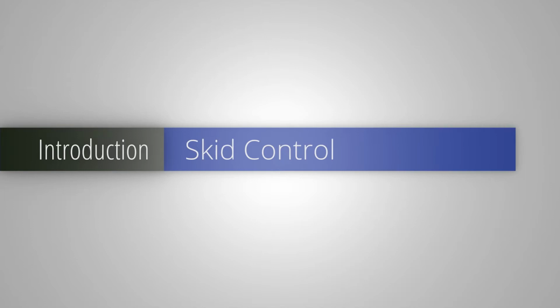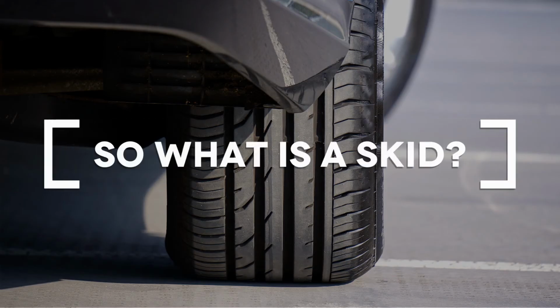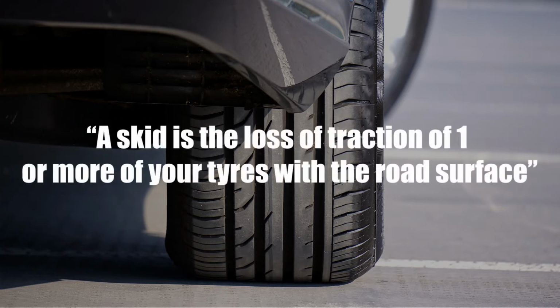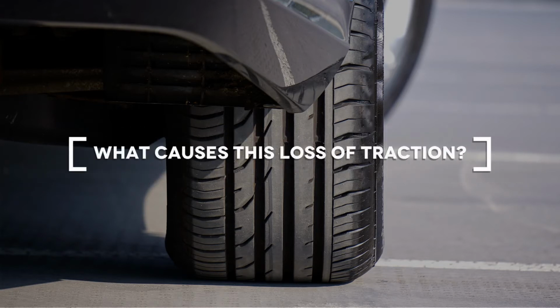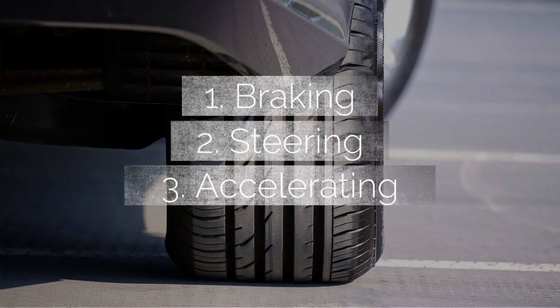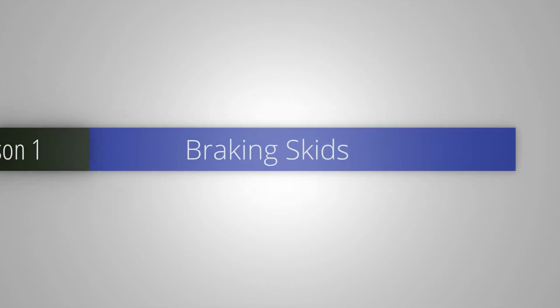So, starting with skid control, the obvious question is, what is a skid? Well, a skid is defined as the loss of traction of one or more of your tyres with the road surface. And there's three causal factors to this: braking, steering, or accelerating. We'll start with the first one, braking skids.